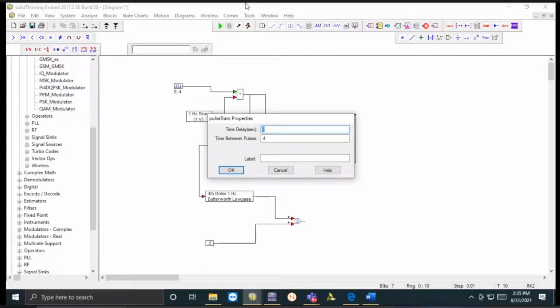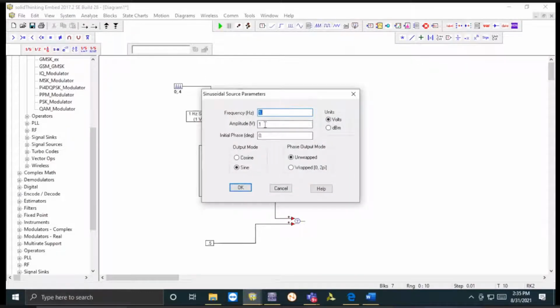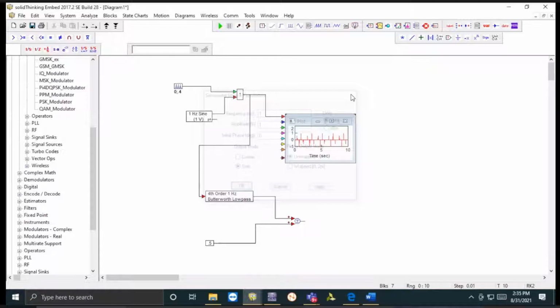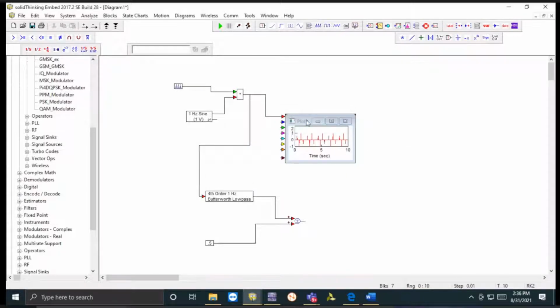So I told you that the time period has to be half that of the minimum component period. So this is 1, right? Frequency is 1, so time period will also be 1, and half of this one is half, right? So it has to be less than half. This is the maximum frequency component value, that is frequency is 1. So it has to be less than half, and so it is 0.4. So when you take 0.4, you will have this type of relationship.